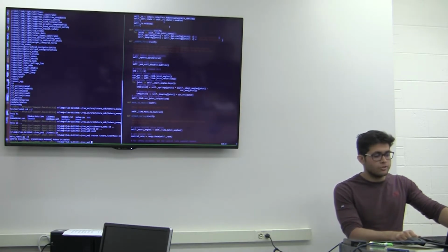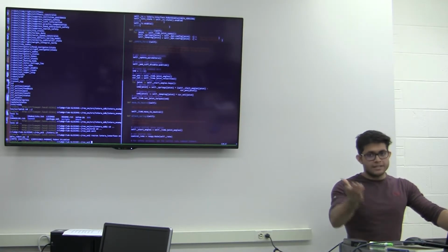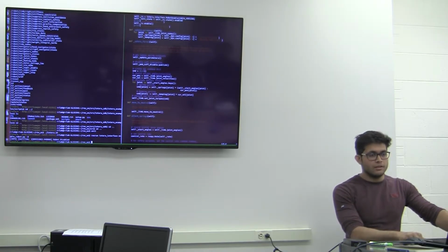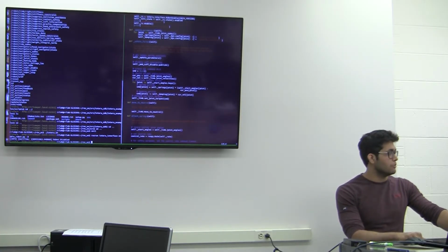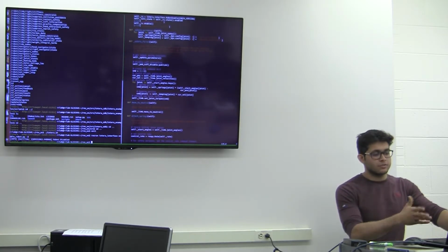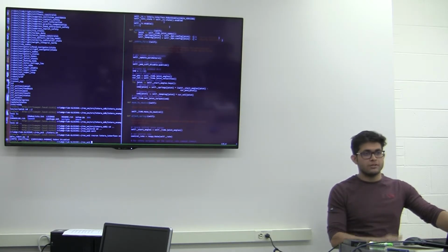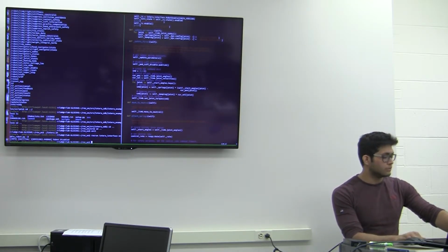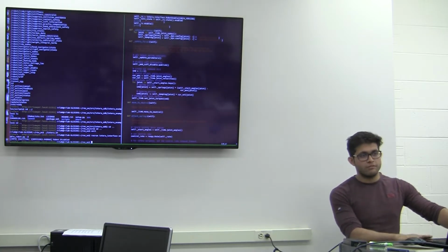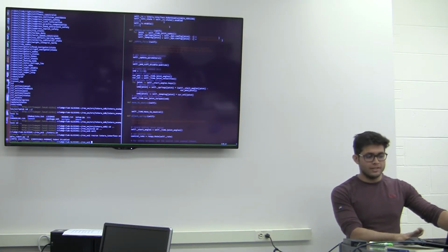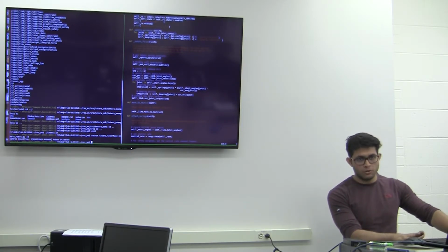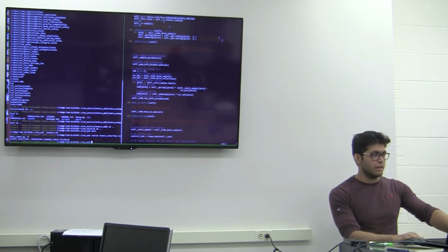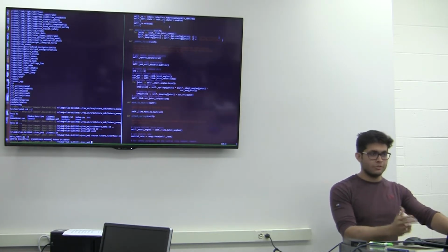It's just a tutorial on how to use Sawyer, but some practices that I think Ivan already went through: if someone else is working in this lab, make sure you don't mess up their part. If you by default have access to some repositories, let us know. We'll make sure it's not accessible to you anymore. And always disable the robot. Always make sure everything else is closed. Always make sure the system is perfectly in its original position and shut down before leaving. Don't leave the robot enabled. Don't power off the robot while enabled. Make sure everything else is back in the state you got it.